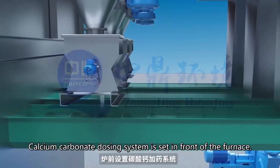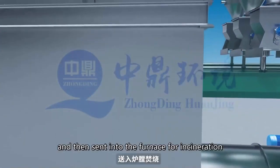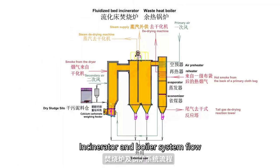A calcium carbonate dosing system is placed in front of the furnace. Calcium carbonate is fed into the furnace after being mixed with sludge by the rear feeder, achieving the desulfurization effect inside the furnace. Flow diagram of incinerator and boiler systems.